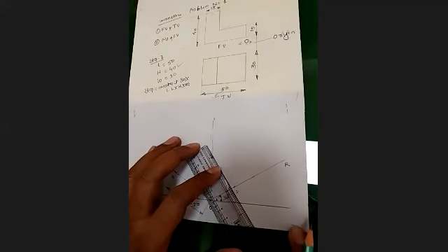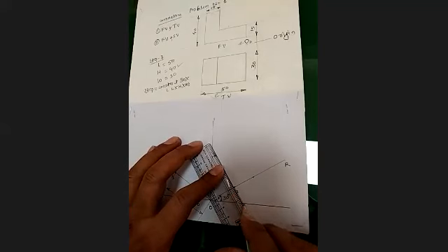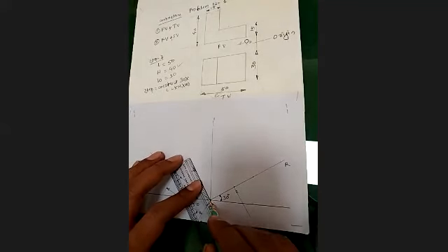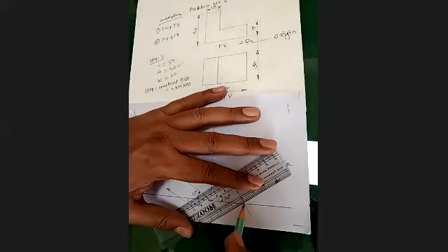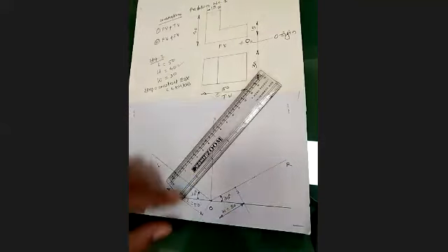There are two ways to give the dimensions. I will explain. Here I am going to give it with one technique, taking these projection lines, dimension lines, perpendicular to those axes, right or left. This is nothing but the width, and in this case, width is 30.